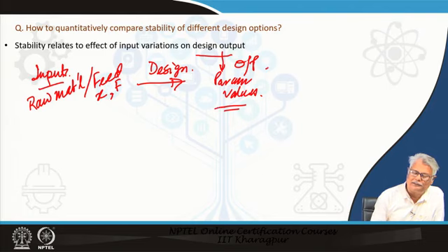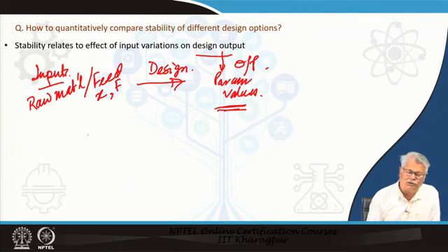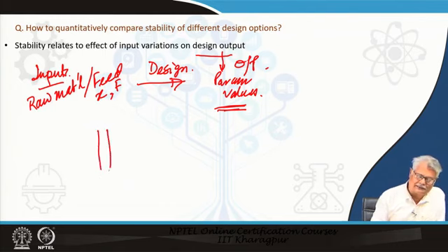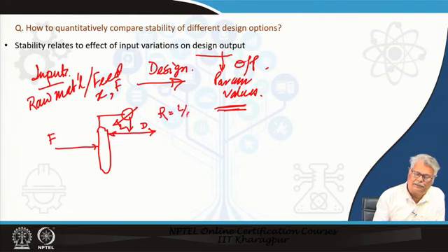So, suppose such a parameter in case of a distillation column design, if we see what all will it be? I will just have a distillation column here. I have a feed rate F, I have a condenser, I have here a reflux ratio which is nothing but L upon D. My reflux ratio is L upon D, and my D has got a composition X_D, and here I have a reboiler where I add heat, generate vapor.